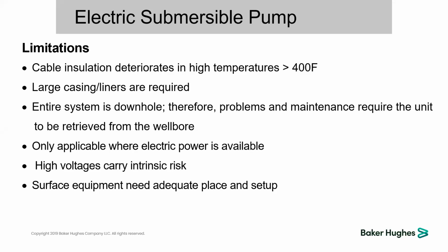So if you have a 4.5 inch casing, you have to install slim downhole equipment, which is not the popular equipment and has its limitations. So case by case, you can install the ESP in 5.5 casing and above. Less than 5.5, you have to install special equipment, which is called slim downhole equipment.